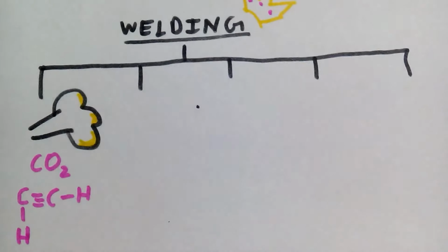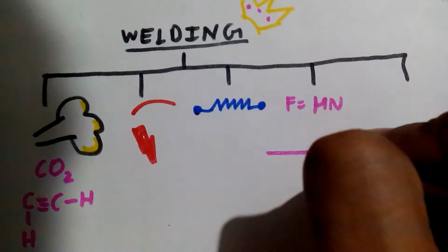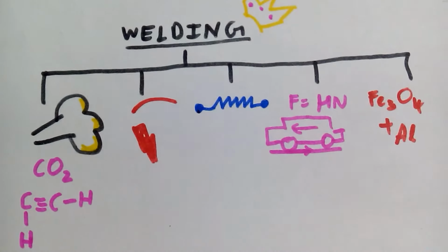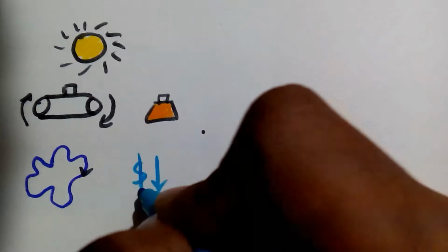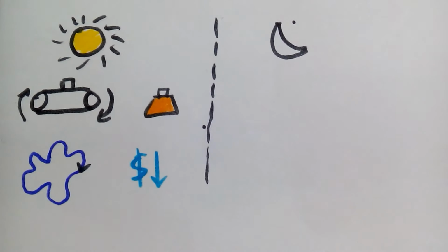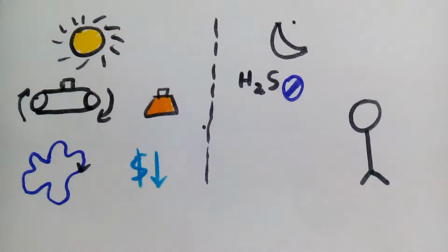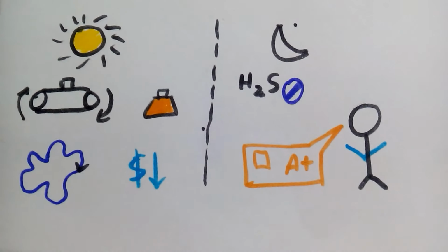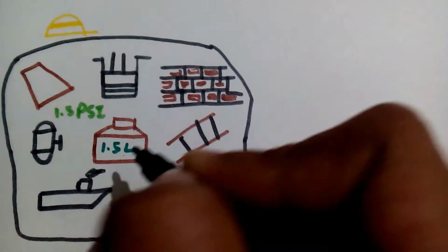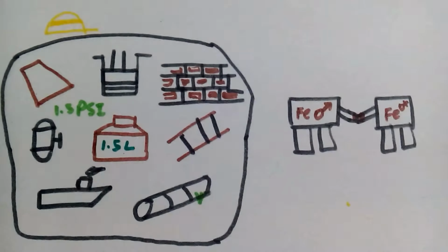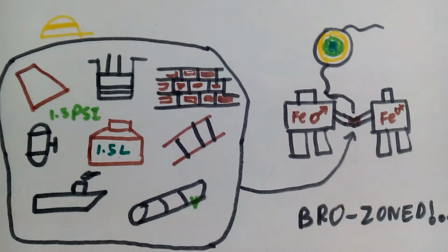It is classified into 5 important types, namely gas welding, arc welding, resistance welding, solid state welding, and thermochemical welding. In general, welding has a large number of advantages, such as mechanizability, near metal strength, maneuverability, and low cost, which easily overshadows its disadvantages like harmful emissions, skilled workmanship requirement, etc. Welding is used in the construction of aircraft parts, automobile parts, building parts, pressure vessels, tanks, railroad equipments, ships, pipelines, and pretty much everything where cheap and strong metal-to-metal joining is required.